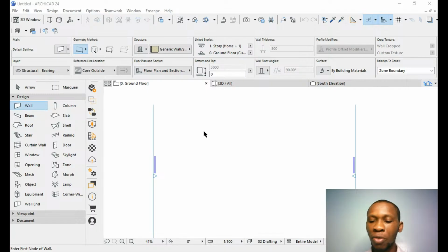If I want to do two of these, let's say two of these can actually give us an A4, right? So if I want to use this A4 to print this document after drawing, what I'll do now is select a scale, so scale 1 is to 200. If I print on scale 1 to 200, depending on the size of the drawing, I can actually reduce the size of the drawing to fit an A4, an A3 rather. Is it A3? A2, no, A5 rather. A5 is smaller than A4. So I can reduce the size of the drawing to fit an A5. And I can also magnify the drawing to fit an A2 drawing paper size.